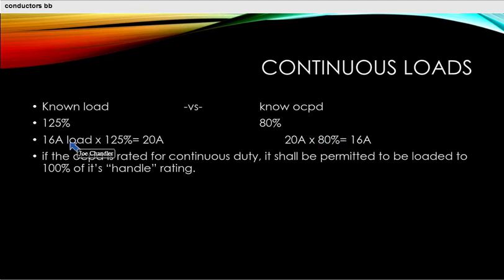If I have a load that I know and I want to know what size wire or overcurrent device, then I increase this by 25%. So again, both of these ways are correct. It just depends on where you're coming from.